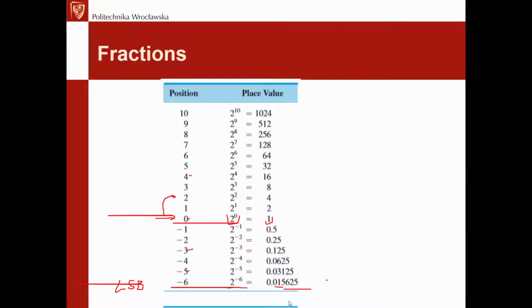Although frankly, in case of fractionals, when I'm using them in my designs, I'm using fractionals in 32-bit precision, to be exact. It's a simplified version of floating points, because floating points we mainly use at 32-bit length.